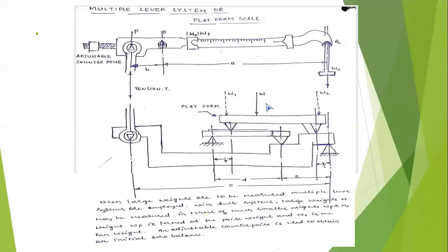45 kgs of rice, keep that on the platform, and then see the balance of the lever that moves up and down. By removing and adding the rice to the bag, bring this lever to the standstill condition, in the place left for oscillation of the lever. When this comes to the exactly horizontal position, that indicates the weight of the rice that is in the bag.